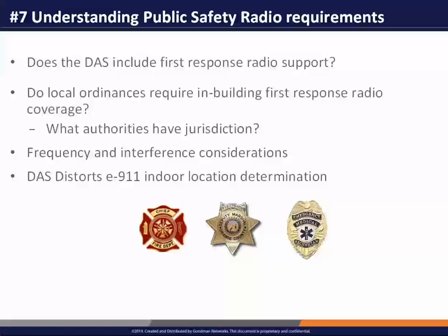Finally, one of the questions that should be asked is, what's the impact of the DAS on E911 location capabilities and requirements? So when you install a DAS, it can have an effect on the ability to find someone who makes an E911 call. And there are very specific guidelines mandated by the FCC that if someone makes an E911 call in a facility, they have to be able to be found within a certain distance of where that call is initiated a certain percentage of the time.